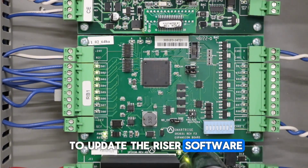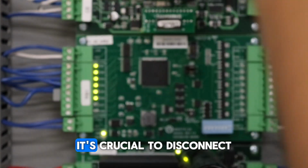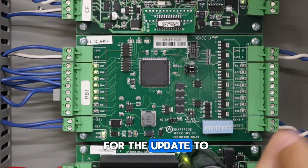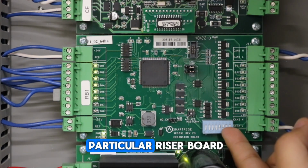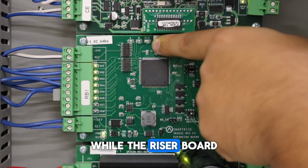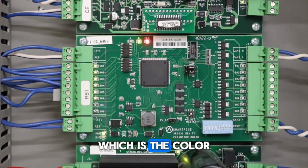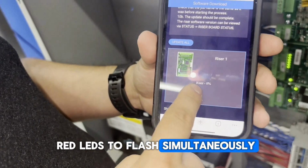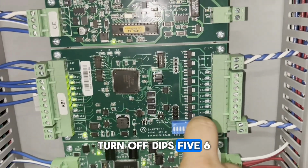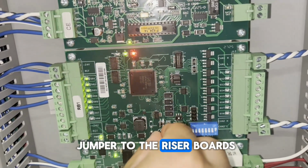To update the riser software, you're going to have to follow these steps. Before updating the riser board, it's crucial to disconnect the WD jumper from the board. This step is essential for the update to work correctly. Now, to update a particular riser board, turn on DIPs 5, 6, 7, and 8. While the riser board is updating, watch for the B, which is the color green, and the fault, which is the color red, LEDs to flash simultaneously. To update the board, click Update All. Once the update is complete, turn off DIPs 5, 6, and 7, then cycle power. Finally, rewire the WD jumper to the riser boards to complete the